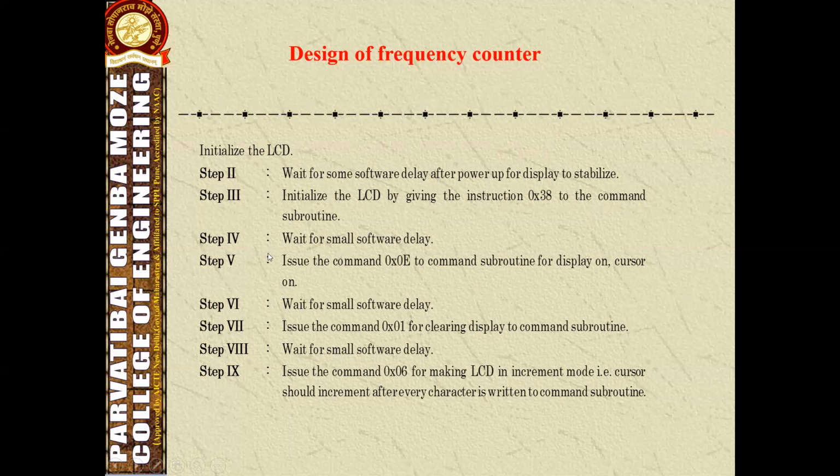After interfacing, after we are done with the connection, we first have to check the LCD. How? We have to initialize the LCD, then wait for some software delay after power up. Software delay is nothing but the delay instructions we have written in a program.